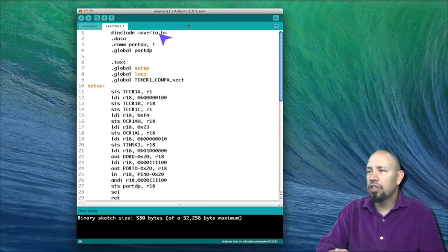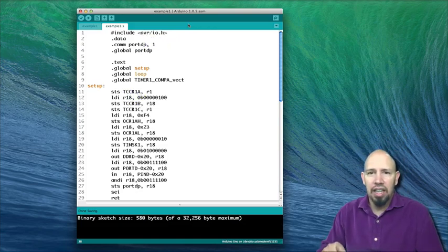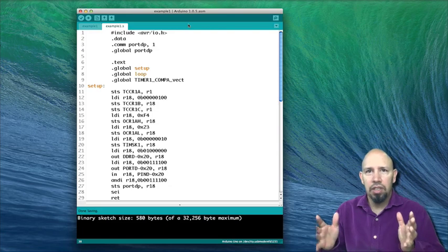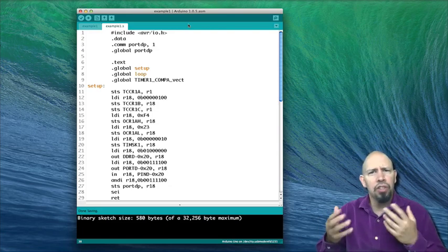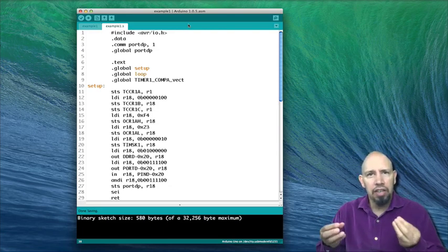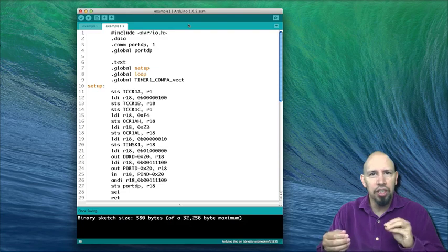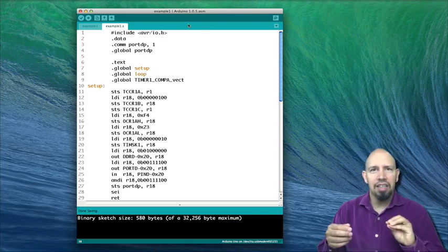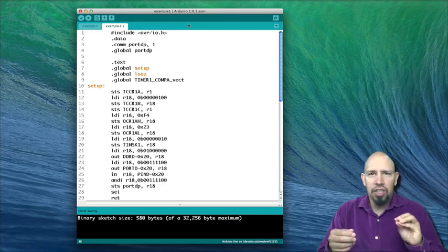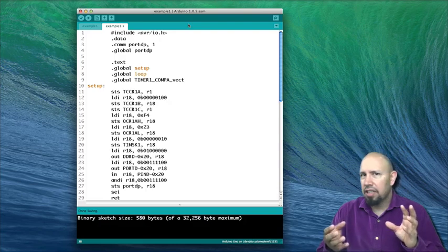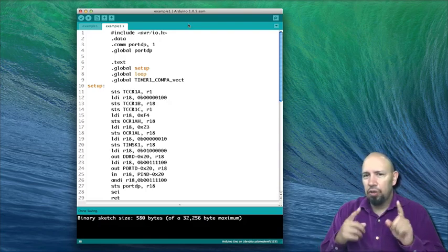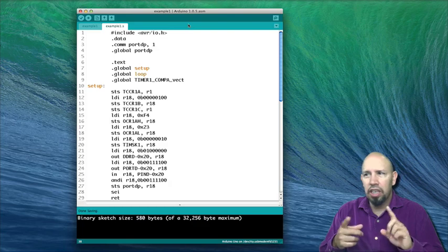and so this is helpful in that it allows us to use, for example, the register names instead of the address, and that is a helpful thing. And also, it's informative. It actually makes our code more informative than just giving some address. If you just give it the address, it's like, okay, there's an address, but then you have to use the table to look up the address, and if you're trying to debug the code, then you have to go backwards to get the address.